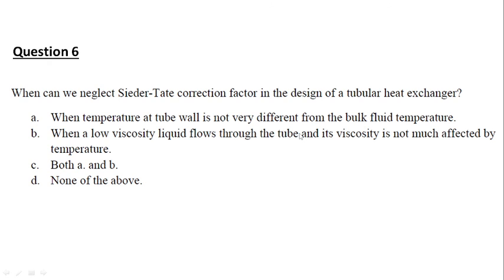Like you told now, you need to maintain it at 37. Hello. Okay, yes, I am listening. So the thermocouple will measure the fluid temperature, and accordingly the heat will be produced. Like if we need to increase the temperature, then the heating will be done on the surface. Okay, so one thermocouple and one temperature controller is required.